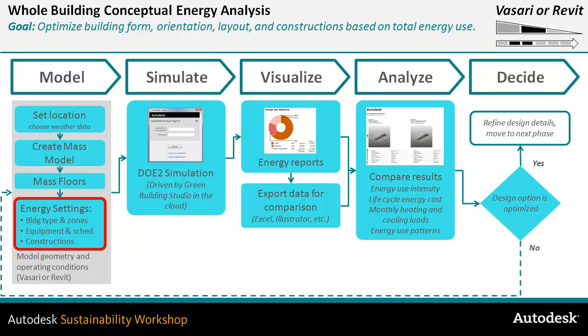When you specify the type of building, say an office, there are assumptions made with regard to the lighting and equipment, and that contributes to the loads for the building itself. You know, they're generating heat. You're also specifying the materials, and that has a U value or an R value that has to do with the level of insulation. And so you're very quickly establishing some defaults on the macro scale, and later on, once you've started at this macro scale, you can come back.